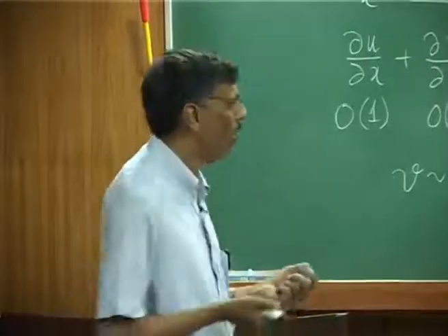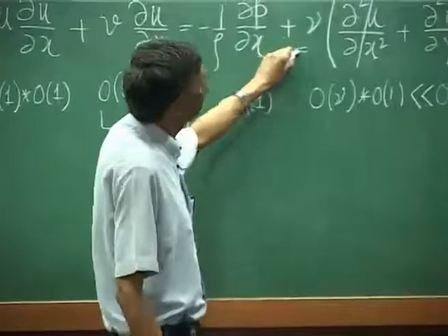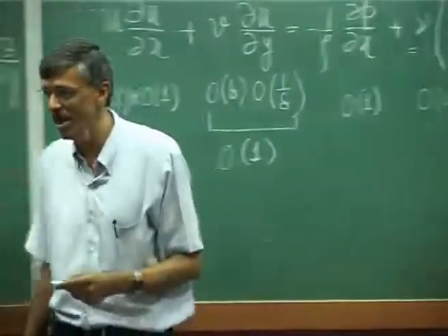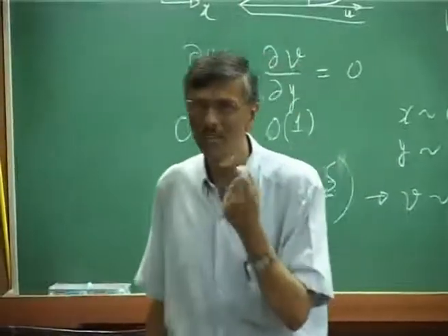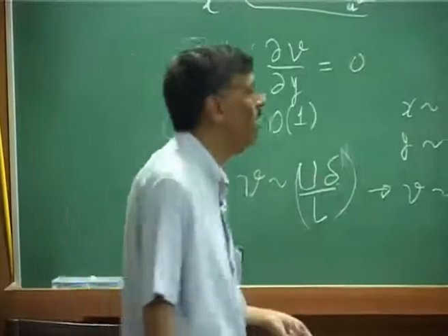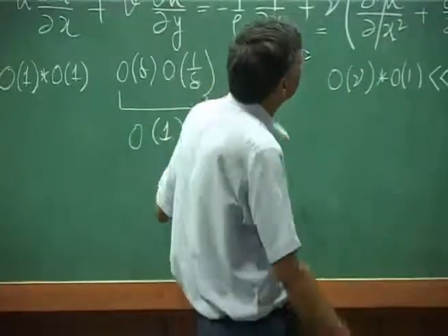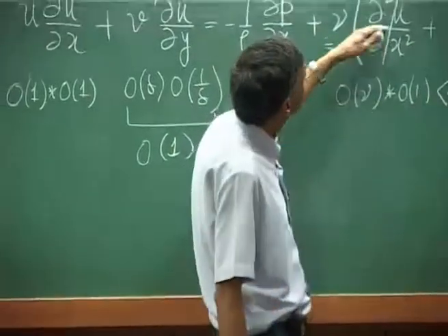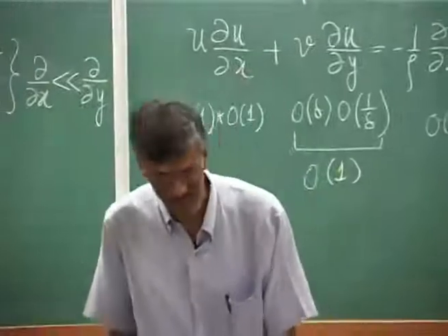Okay. So, as we have said, the smallness of this quantity contributes to the formation of the boundary layer. The property of the solution comes when the highest derivative is multiplied by a small quantity, that is exemplified here. Although this order of magnitude analysis tells us that we can drop this term in comparison to the second diffusive term.